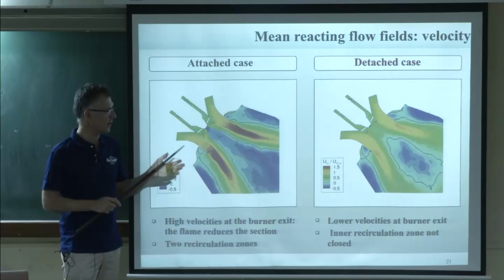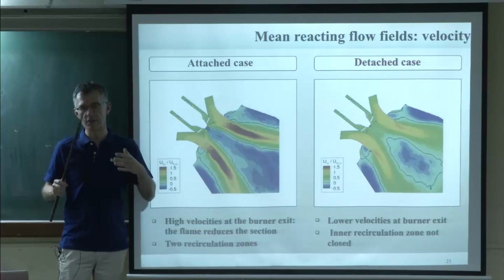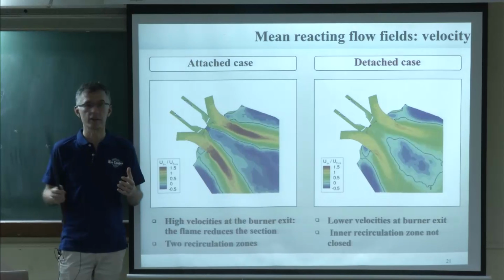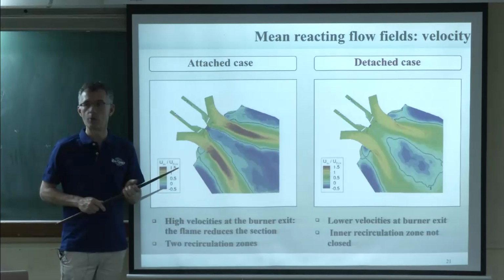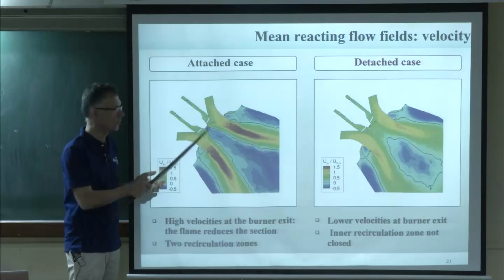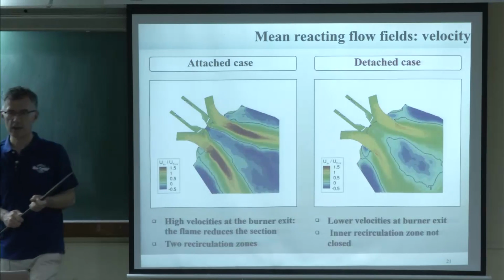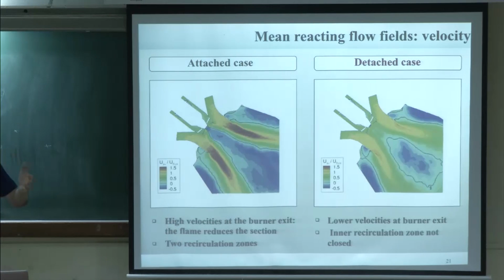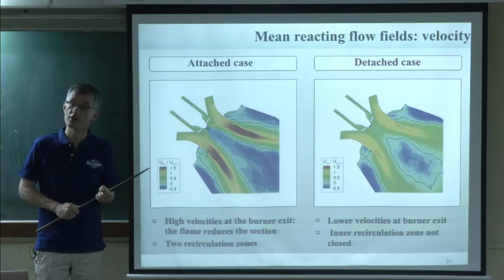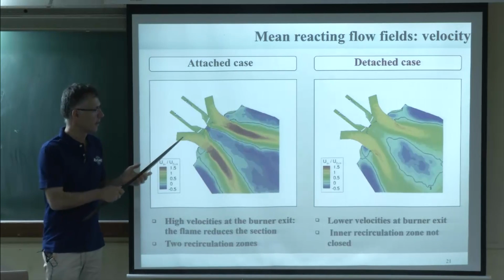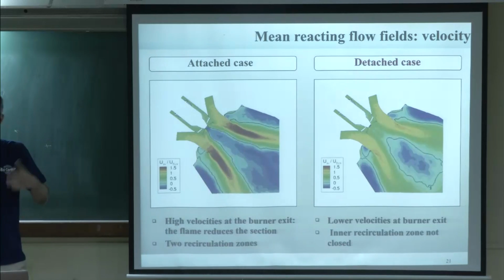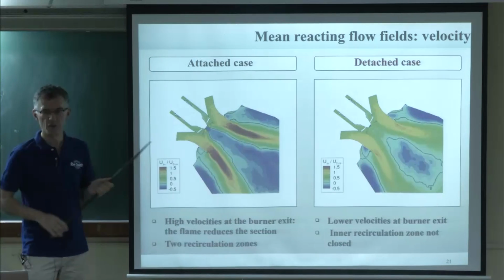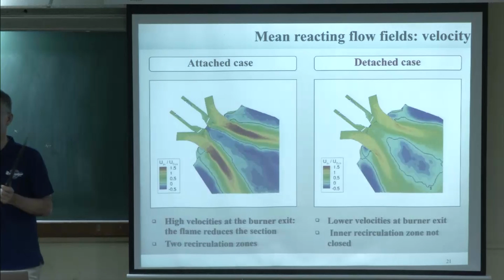And in the future, we're going to need to have all these things coupled to the LES. We cannot do LES in a blind way as far as the mesh is concerned. You cannot just hope to put a mesh and let the code run and hope for the best. It's not going to work. We need to control the mesh. Of course, if you put 5 billion points, maybe you can go for that, but that's not going to happen, because we know that very big meshes everywhere is just going to be too expensive. So we need to save a little bit of money there.